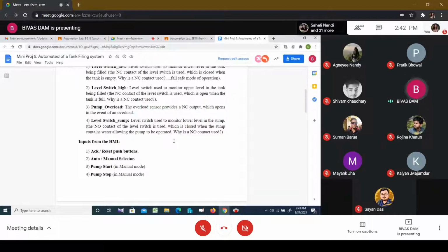So even after T plus 5 units of time, if the pump is not automatically off, we must indicate that some error has occurred in the pipeline, or some malfunctioning is there. So I must now switch off the pump. So that's called the timeout situation. So this timeout situation should also be incorporated in our system.